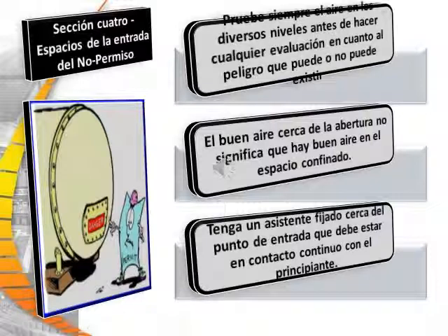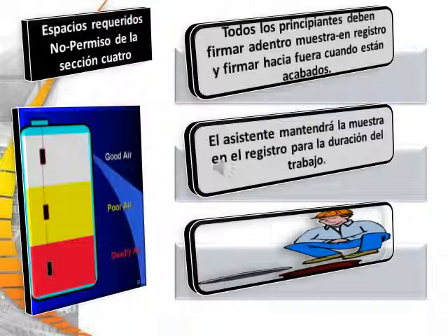Have the attendant posted near the entry point, who must be in constant contact with the entrant. All entrants should sign in the log and sign out when finished. The entrant shall maintain a sign-in log for the duration of the work.